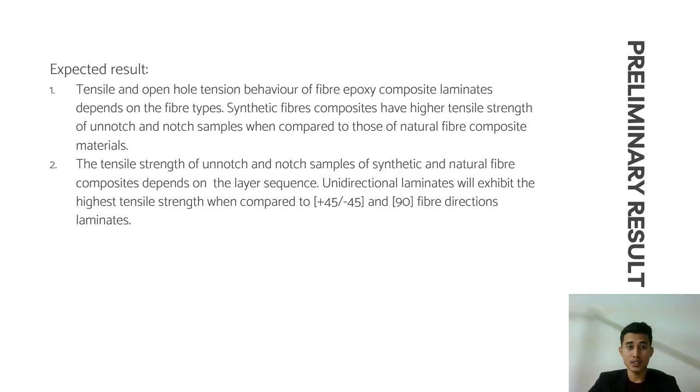Second, the tensile strength of notch and open hole samples of synthetic and natural fiber composite depends on the laying sequence. It is expected that the unidirectional laminates will exhibit the highest tensile strength when compared to the 45 degrees and 90 degrees fiber direction laminates.